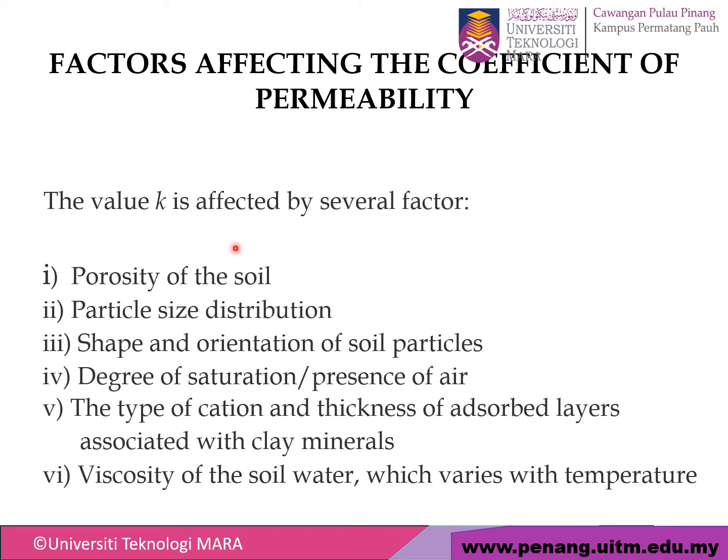The value K is affected by several factors. Porosity of the soil: the more porous the soil, the higher the value of K. Particle size distribution: this refers to the size, whether coarse or fine. For coarse soil, the K value is higher compared to fine soil. Shape and orientation of soil particles. If you compare dense soil and loose soil, you will see that for loose soil, the K value is larger compared to dense soil.